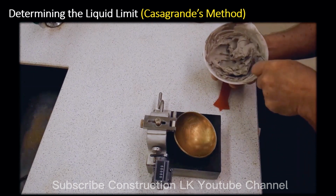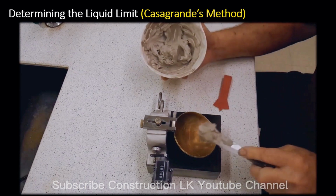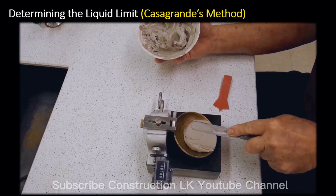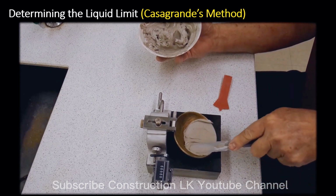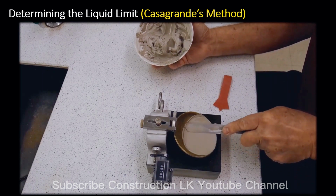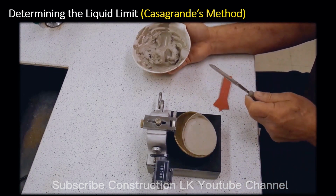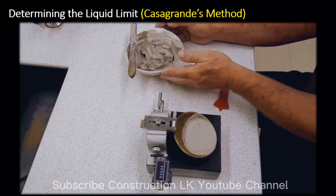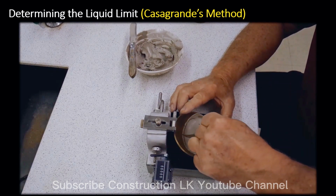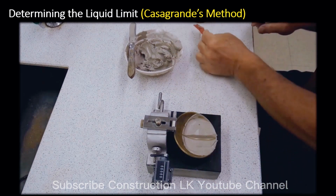Then a portion of the prepared soil shall be placed in the cup of the liquid limit device and spread in the cup to a depth of 10 mm at its deepest point. Also make sure to form an approximately horizontal surface. Care should be taken to eliminate air bubbles from the soil pat, but the pat should be made with as few strokes as possible. Then a groove should be made in the soil pat by drawing the tool through the soil, on a line joining the highest point to the lowest point on the rim of the cup.